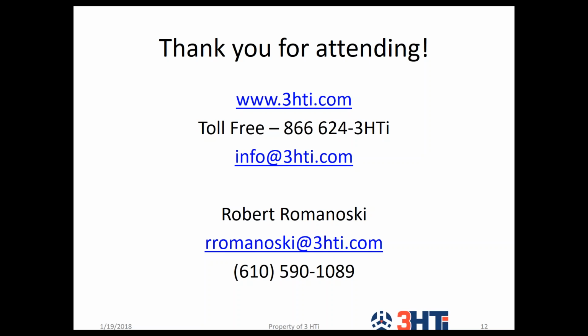Question that came in: does one person or company need to maintain the master assembly? Yeah, someone is going to need to maintain that master assembly, and you're going to check that into your PDS system like you normally would. You saw within the demonstration, when I shared that out to the multiple engineers, one thing that they did at the end was they checked back in their specific model. When they check that back into their PDS system, that's going to incorporate the changes back into the large assembly, which is going to be residing within your PDS. So you would have someone denoted, maybe the main engineer, who's going to take care of that main assembly. When they open that back up, since everything was checked back in, those changes are going to be readily available when they regenerate.